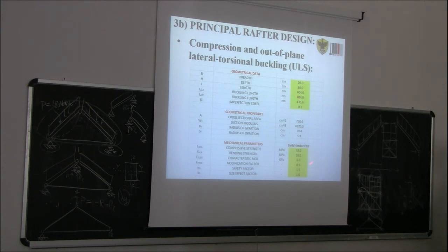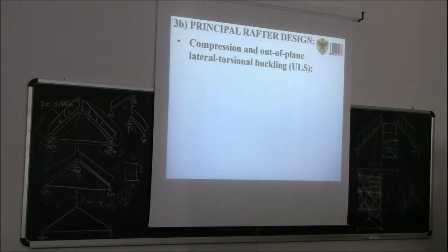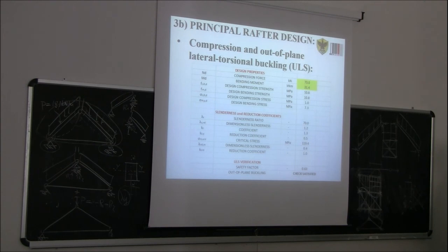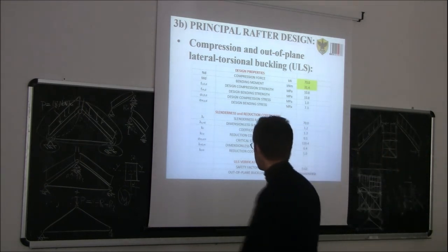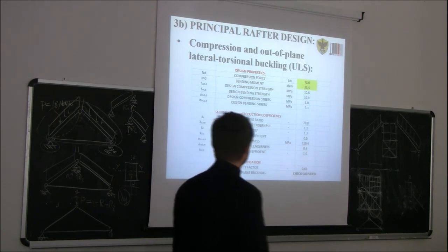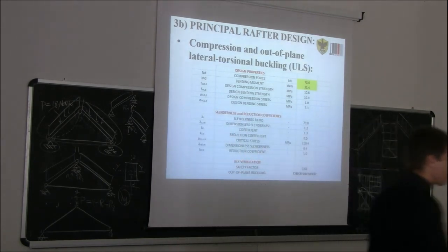Again, if you replace all the properties inside here, we get to see a safety factor of 0.63. This shall be less than 1, so lateral torsional buckling coupled with compression is not an issue for this kind of structure. Okay?